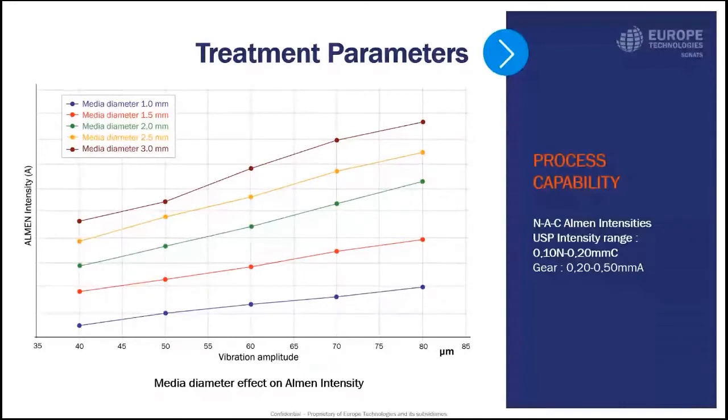The peening time is also, as conventional, automatically controlled to ensure that the coverage time is accurate. USP complies with standard specifications AMS 2430, J442, J443, J2277.